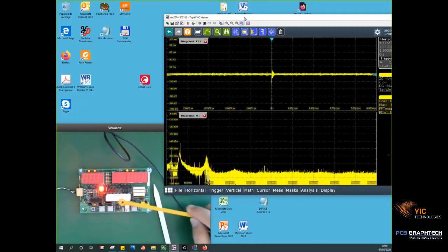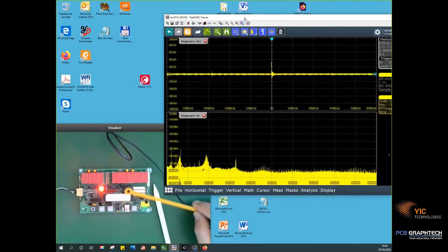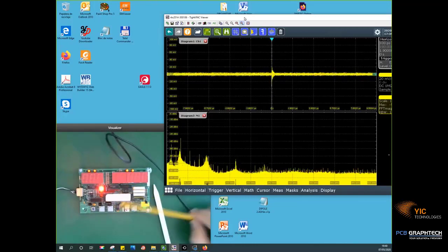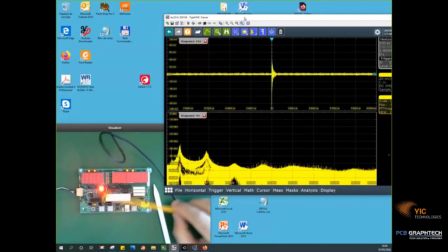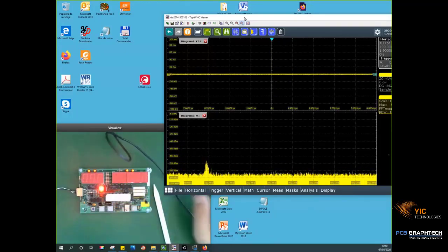You can go and find specifically some signal, and then you can make some changes in your circuit or in your software to reduce or to kill some specific frequency. So this is only to introduce you to the idea of a near-field probe. I use near-field probes every day in many of my analyses.